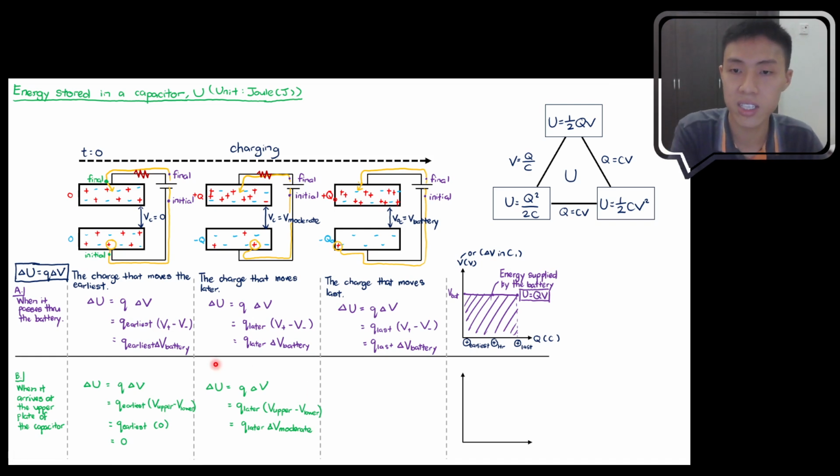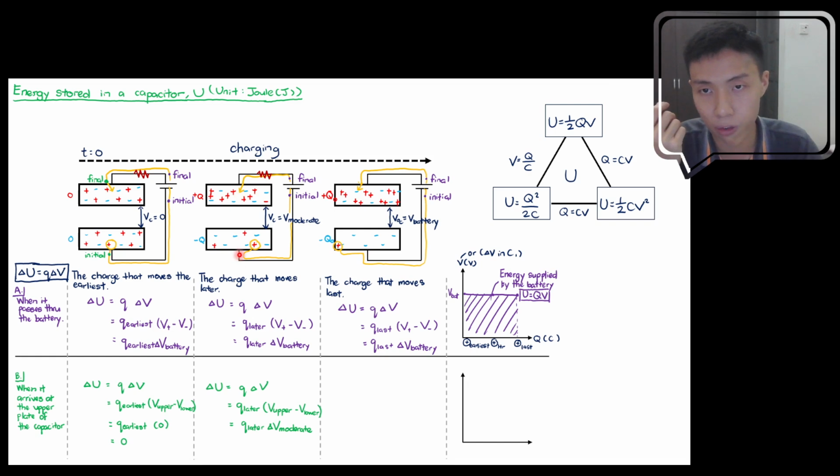So let's say if this thing is positive 2, and this thing is positive 5, then what it means is that from here to here, there's a gain of 2 joule of energy for every coulomb. Okay, there's a gain of 2 joule when you move from here to here. But you know that you gain 5 joule over here, as calculated over here. You gain 5 joule, which means to come back to the upper plate, you have to throw 3 joule away so that you can come back with 2 joule. So when you throw the 3 joule away, you throw it at the resistor.